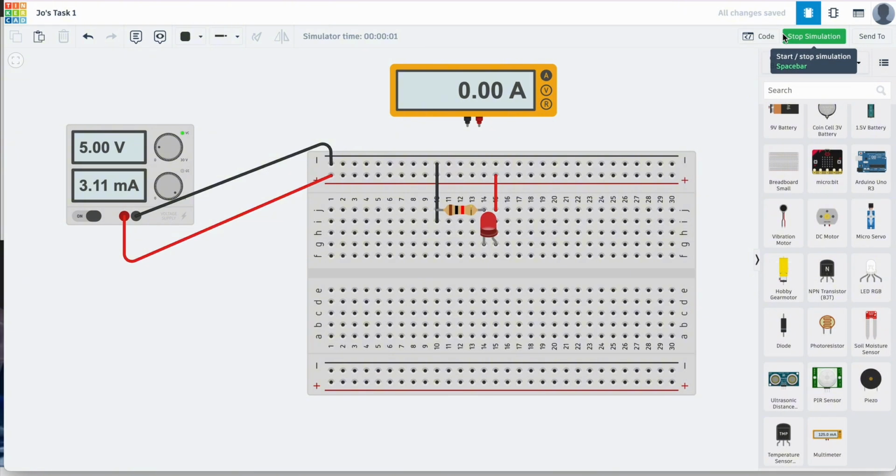Okay, so the moral of the story is if you're using the ammeter, you have to put the 2 little terminals directly on either side of where you want to see what the current is going through. If you don't do that, it basically will bypass anything upstream or downstream of where you place the 2 terminals and just read the current through that area. Okay, hopefully that kind of makes sense.